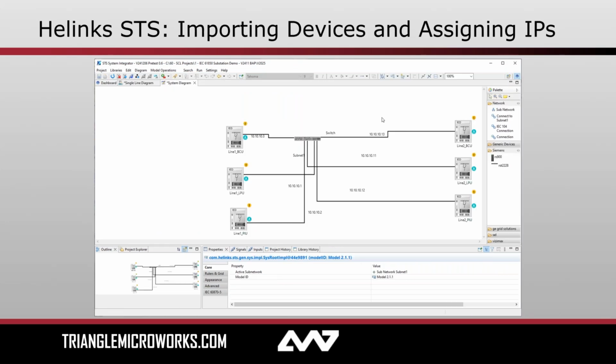Finally, at least if we're following the more top-down paradigm, we're going to pick out our IEDs. So once we pick a manufacturer and a specific IED model, we're going to load in the ICD, or the IED capability description that vendor is going to provide us, or that we might export from their tool. These will be loaded into our system configuration tool as we've done here, and then we have the opportunity to associate them with functions,